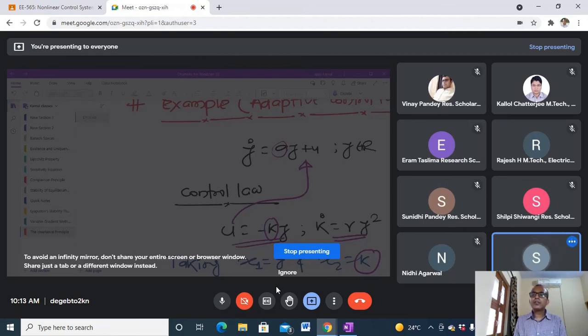The third thing is that suppose you have multiple equilibrium points, then I cannot apply Lyapunov analysis, but I can apply LaSalle's invariance principle. Due to that reason, LaSalle's invariance principle has extended Lyapunov analysis in different dimensions. One, they remove the requirement of negative definiteness, and with all three they are precisely able to calculate the region of attraction. Second, if I have connected equilibrium points, then how to talk about stability. And the requirement of positive definiteness of V(x) is also relaxed in this particular theorem.